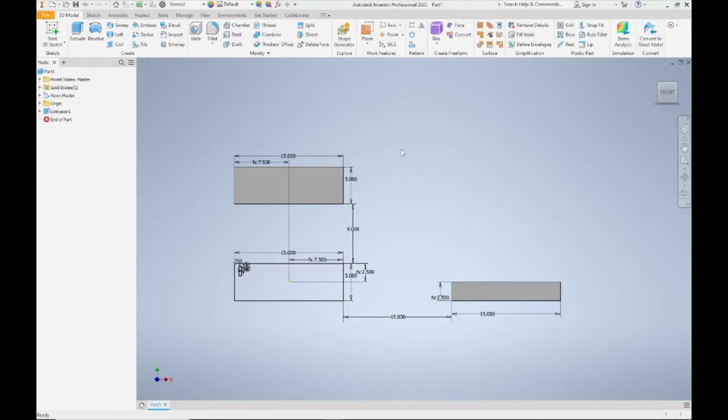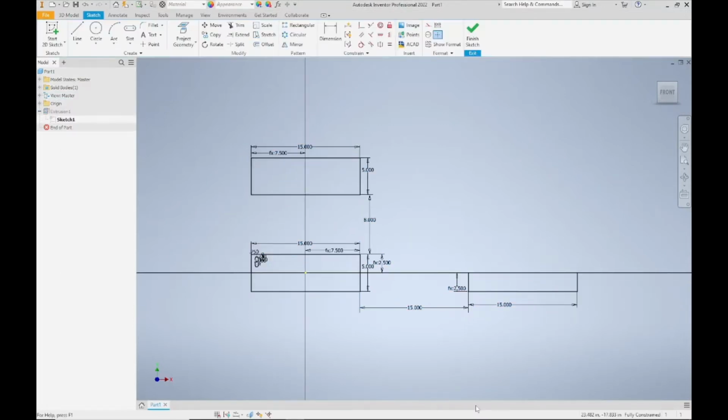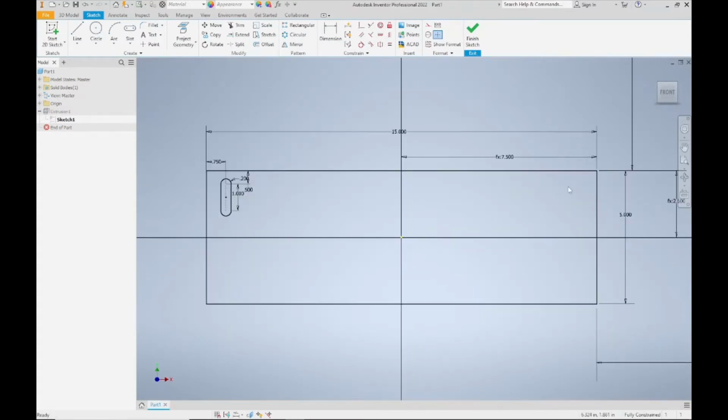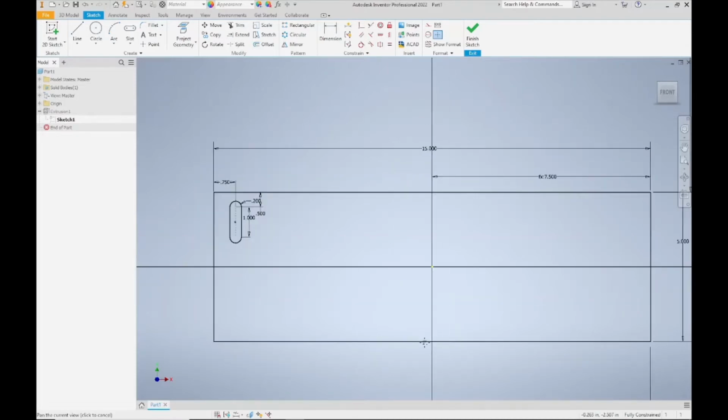So I have open here just a couple of shapes that we're going to be working with. I'm going to go into my sketch 1 and edit sketch. Let's start with this bottom rectangle here on the left. We can see I have a rectangle drawn. It's fully constrained. All of my lines are black. And then we can also see that we have a slot shape here, also fully constrained and located and sized here. So rectangular patterns are used when you want to create copies of geometry that are all in line with one another. So a linear version of copies, so to say.